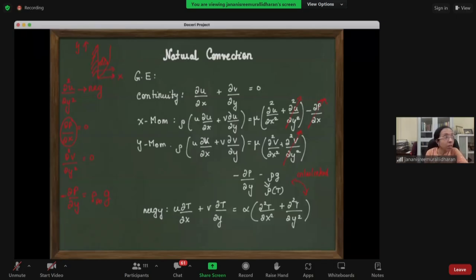Then I also say that the V momentum equation, where V is the velocity in the y direction, right? So the V equation can be neglected in the y direction. All these are neglected compared to the significant movement in a particular direction. Okay, so you have dou square v by dou y square also equal to 0. I can neglect it. Now, the important thing is this condition here, which is dou p by dou y. Okay.